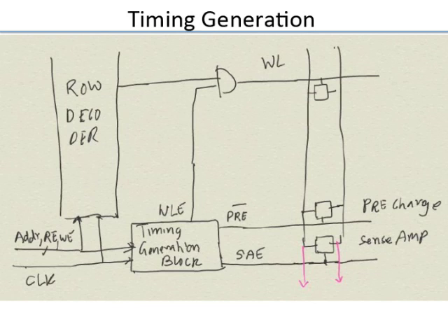Here you don't necessarily have sequencing elements or flop elements, but data items or data tokens are in transit, and multiple data tokens are available. It turns out with wave pipelining, there are very stringent conditions that need to be preserved. There has to be a lot of symmetry, so typically you don't use wave pipelining for general logic, but it works well for memories because there's a lot of symmetry. For example, from the decoder input to the decoder output, it's essentially symmetric.